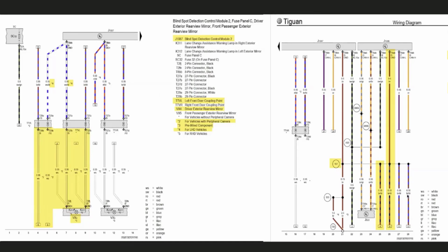If we follow track 26 over here, look where 9 picks up on 26. It actually says, or maybe I followed that wrong. I might have followed that wrong. No, I followed that right. 26 right here, sorry, brown blue. I read that wrong. Yeah, you're looking for the blue box with 9 in, yeah. So you follow it to brown blue, and that goes actually to a ground. So it can't have 2 grounds and work, right? That's not how that works. So they drew it wrong, as a matter of fact.